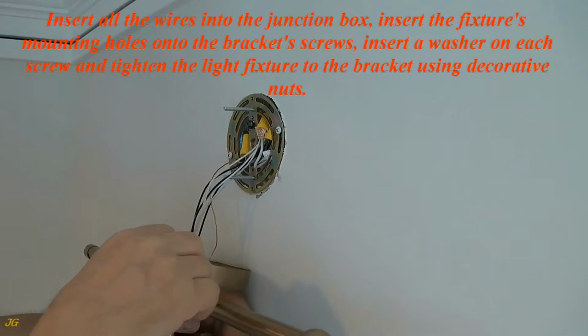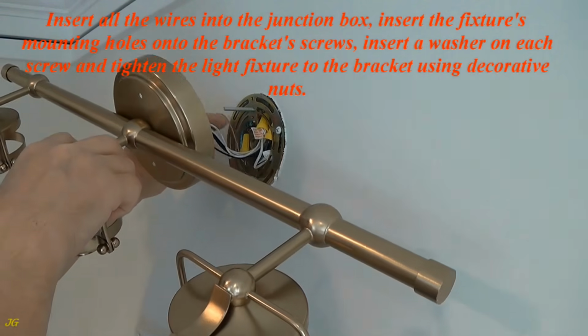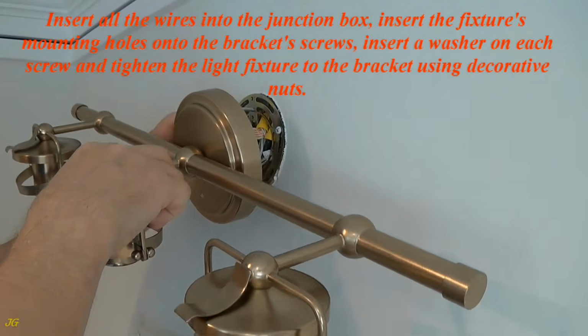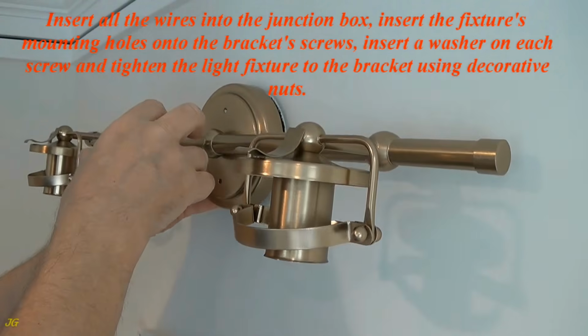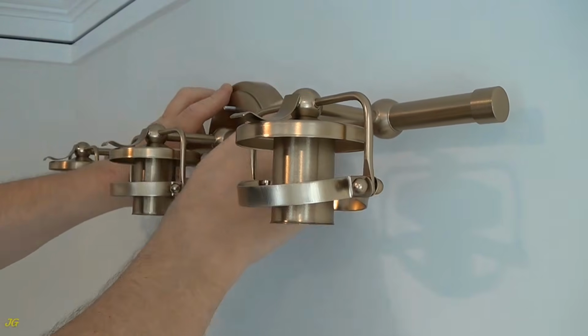Insert all the wires into the junction box. Insert the fixture's mounting holes onto the bracket screws. Insert a washer on each screw and tighten the light fixture to the bracket using decorative nuts.